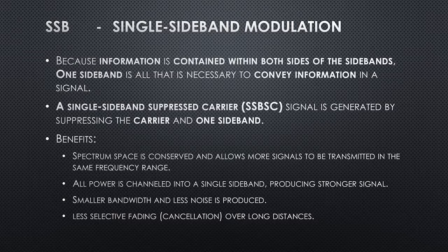Second, all power is channeled into a single sideband, producing a stronger signal. Third, smaller bandwidth and less noise is produced. Fourth, less selective fading or cancellation over long distances.